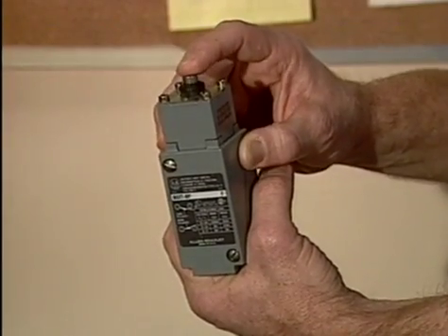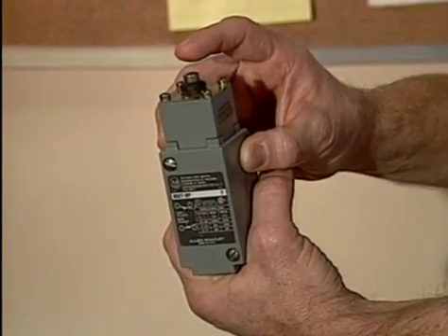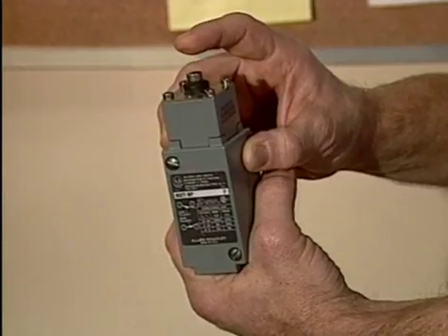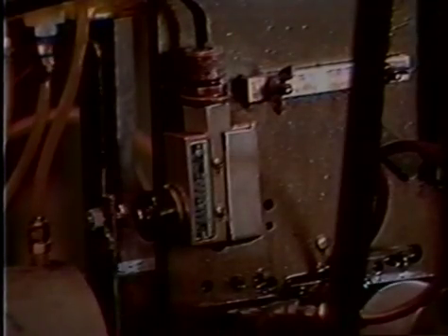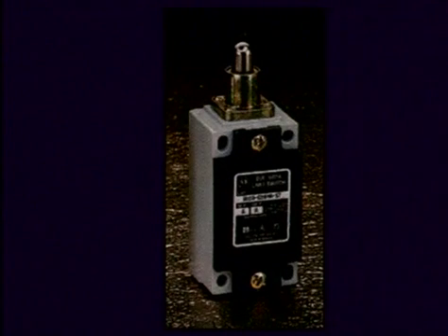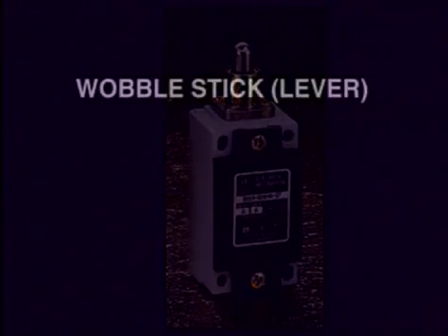The plunger actuator requires linear operation for its movement, which can be from the top or from the side. These actuators may also have a top roller in the mechanism, which allows a cam to move past the roller and push into the switch. The plunger actuates the switch assembly by pushing, and care must be taken that the limit switch is not pushed beyond its travel specifications because it could damage the switch mechanism.